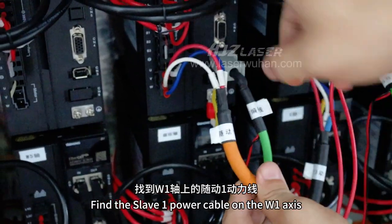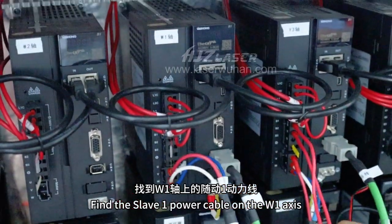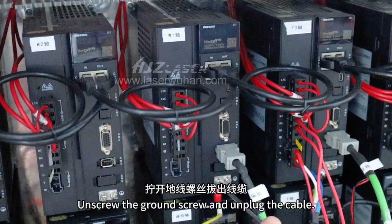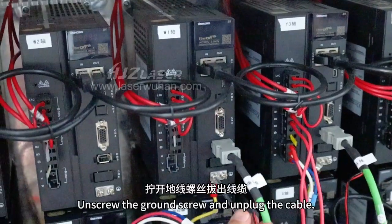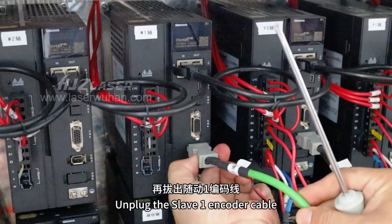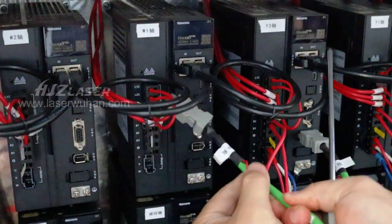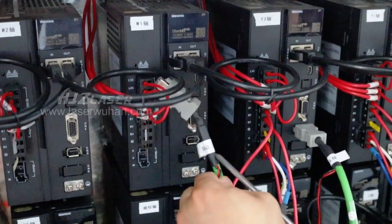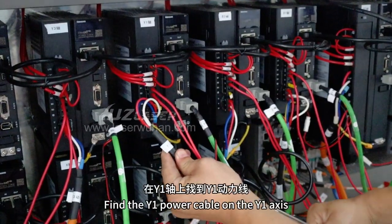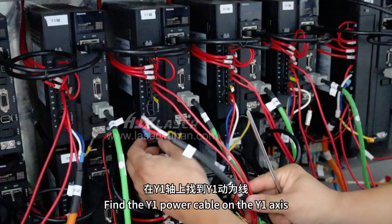Find the slave 1 power cable on the W1 axis. Press the clip and unplug it. Unscrew the ground screw and unplug the cable. Unplug the slave 1 encoder cable. Find the Y1 power cable on the Y1 axis.